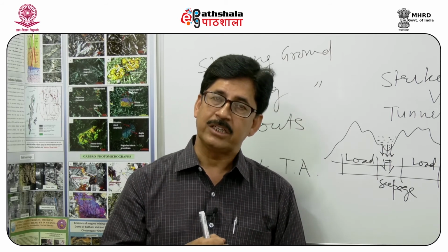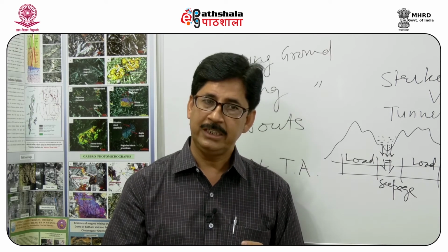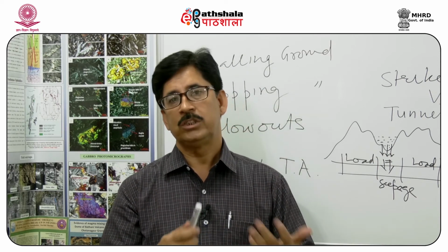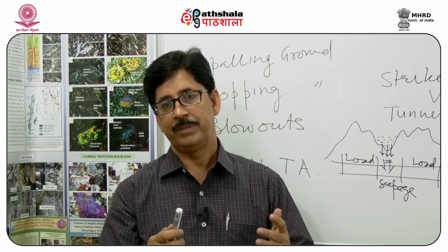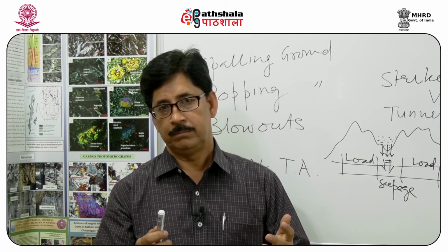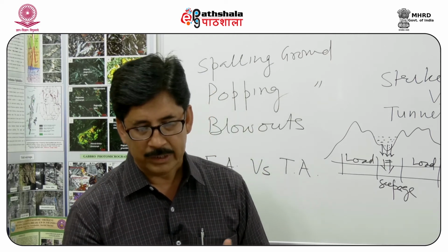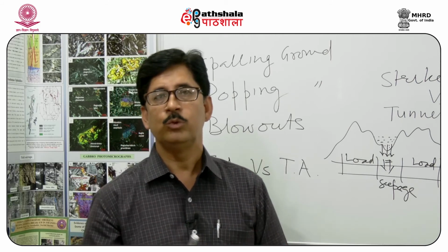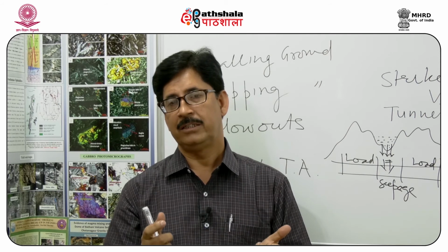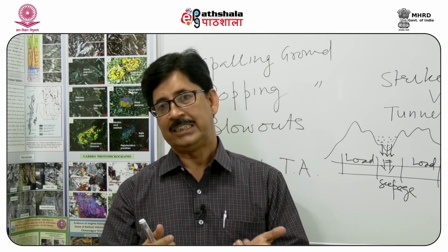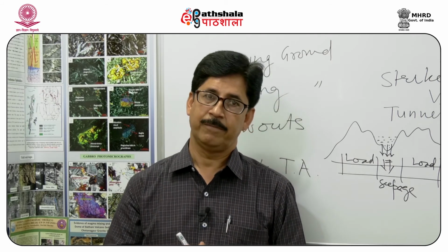Now when we excavate, we have to provide support depending upon the rock mass quality. The traditional old support system was based on wooden legging, wooden frames, wooden posts and sills which were installed in the rocks in different patterns, and then steel came, and then steel arches have been used for supporting.